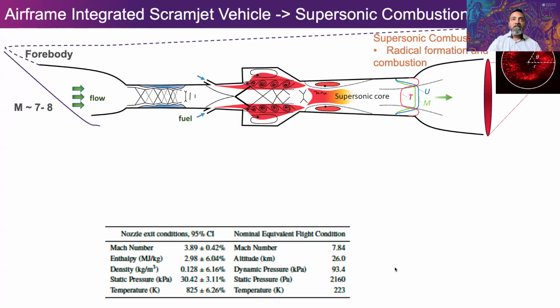So the question was, we need to test these things. Okay, so how do we test these things? Historically, we've been used to just putting in the full three-dimensional scramjet and testing it. We took a step back from that, particularly when we didn't understand what was going on with the fuel air mixing with hydrocarbon fuels. We said, let's just focus on the part that we need to understand, which is fuel air mixing and combustion. So let's design a combustor that's suited for this purpose. Instead of doing the full three-dimensional complicated inlet, let's choose an axisymmetric simple geometry. So that was this geometry.